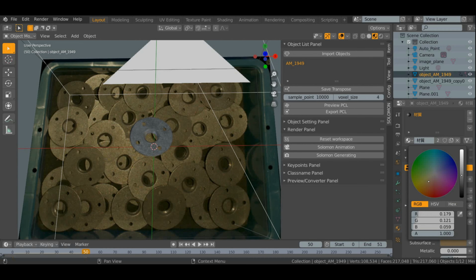In case the selected color is not optimal, you can select another pixel or slightly modify the selected color, like I am doing by increasing the clarity a little bit. Once you are sure that the selected color is the best option, you need to remember the RGB code for each section. Before continuing, you can return the RGB values to 0 for all the sections, because we are changing the color of the surface of the object and we don't want to modify the object. We want to adjust the light to display the correct color.